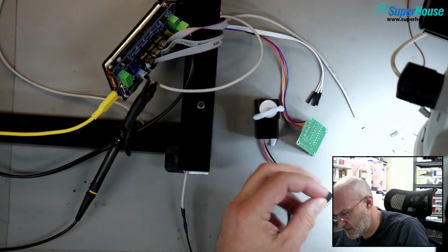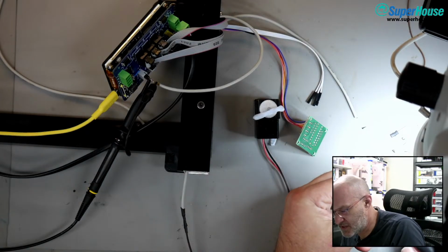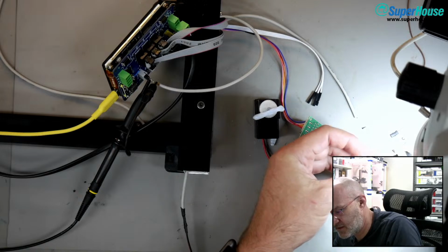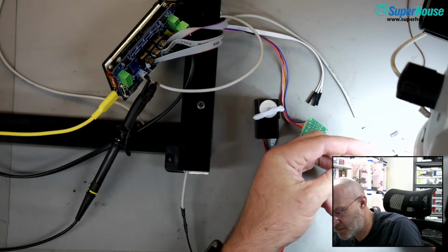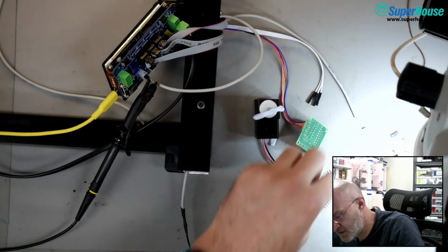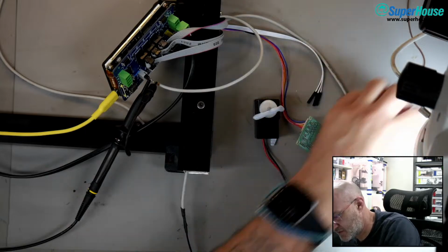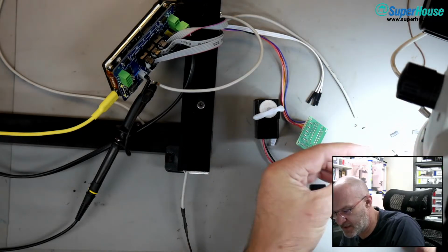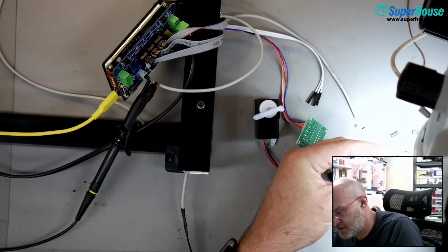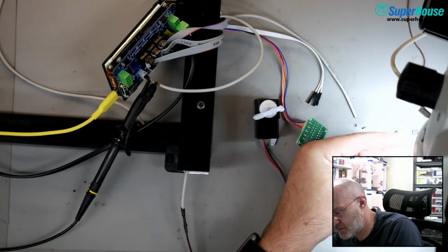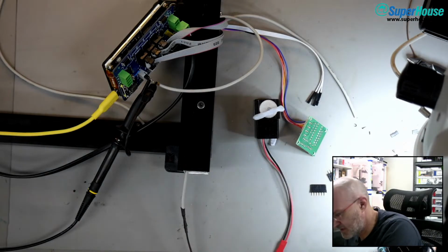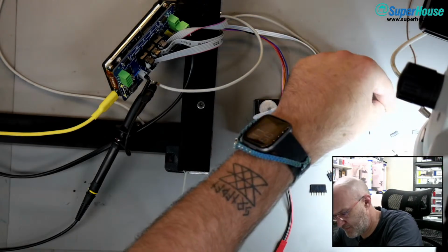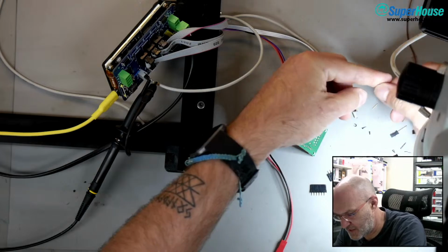And then I need, well, actually this works out okay. So I need a two-way header and a four-way header to go onto the motor driver board. So now I've got my six-way that goes into the controller, a two-way, and then I'll turn this into a four-way, which can go to IN1 through IN4. Boop. And then I just need a bit of wire. There, what a mess.